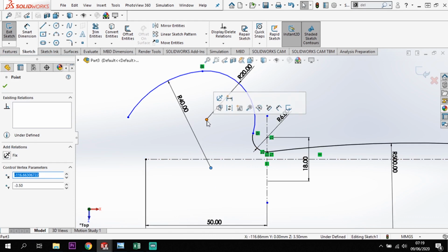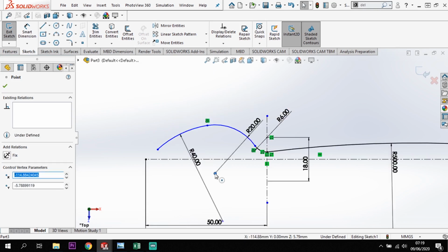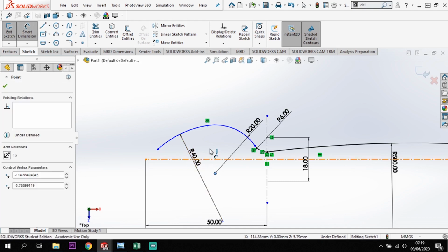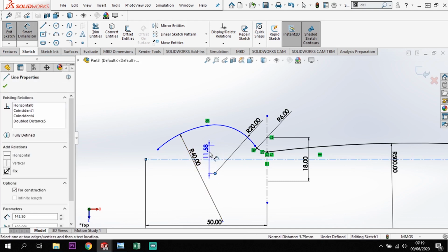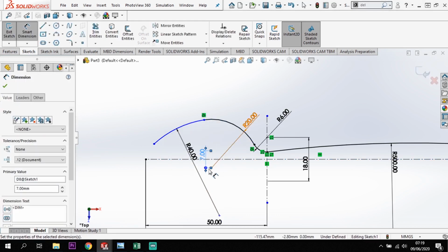Okay, so I'm just going to manipulate this again, dragging this down, and there we go, that's looking a lot better. So I want this position here from the 20 to there, to have a dimension of 7mm across. So we've got the 20mm radius here, with a 7mm gap across the centre of there. So the mirror image position on the opposite side would be 7.